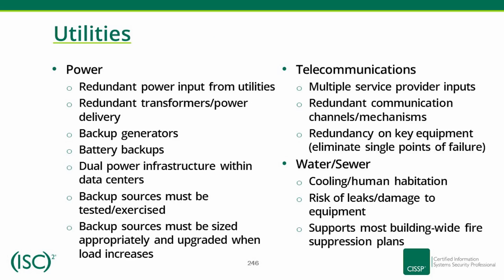Utilities. Power: redundant power input from utilities. Redundant transformers/power delivery. Backup generators. Battery backups. Dual power infrastructure within data centers. Backup sources must be tested/exercised. Backup sources must be sized appropriately and upgraded when load increases.